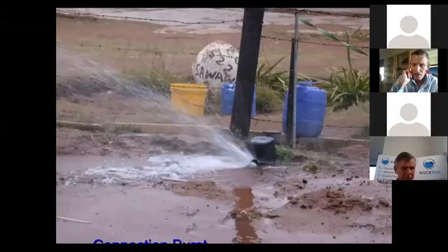Okay, what I'm going to start off with is the introduction to burst and background estimates, and just so that we understand what we're talking about when we talk about leakage. In most reticulation systems, we've got two main forms of leakage: burst leakage and background leakage. And it's quite important to differentiate between the two because they both require a different approach when you're trying to deal with them.